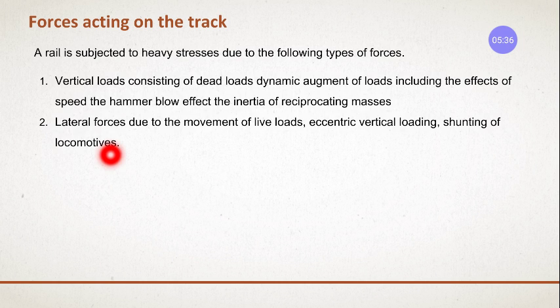Next is lateral forces. Due to the movement of live loads, eccentric vertical loadings, and shunting of locomotives, what happens in this case? There are lateral forces applied over the track. Right?